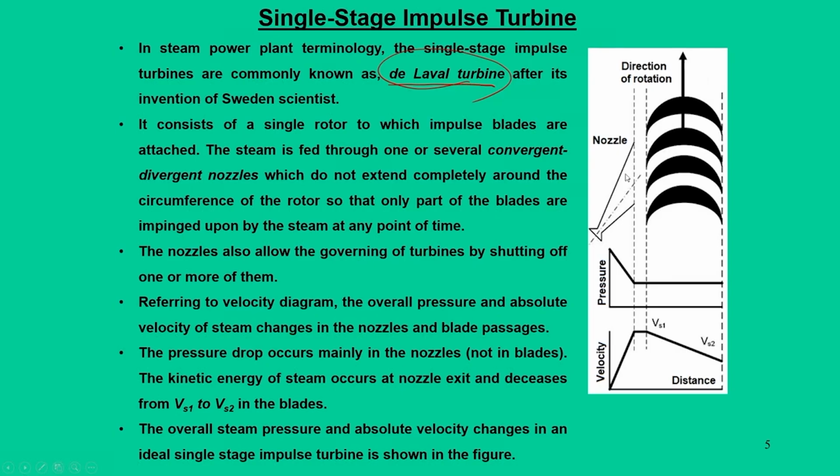Basically, in this figure this one particular nozzle supplies at least 4 blades. Likewise, if you have a large number of blades, we can think about multiple nozzles that can supply the steam to the blades, but at a certain angle, and typically this angle is kept within 20 to 30 degrees. We expect 30 degrees so that it caters to as many blades as possible.